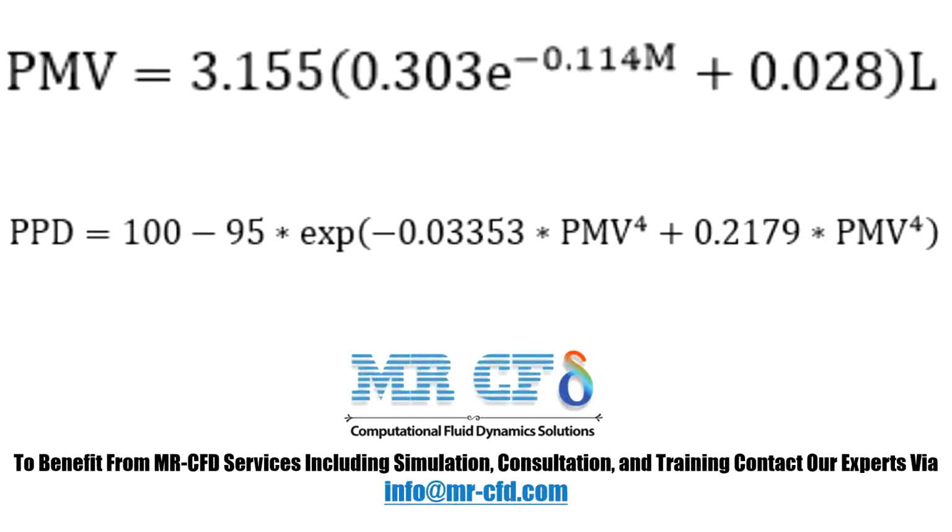Relationships for PMV are defined as a function of 6 variables, including air temperature, average radiant temperature, air velocity, air humidity, thermal resistance of clothing, and type of physical activity. Finally, the PMV relationship is obtained in this formulation as a function of the thermal load, or L, on the body, which is the difference between the rate of metabolic heat production, or M, and the calculated heat loss from the body to the real environment condition.